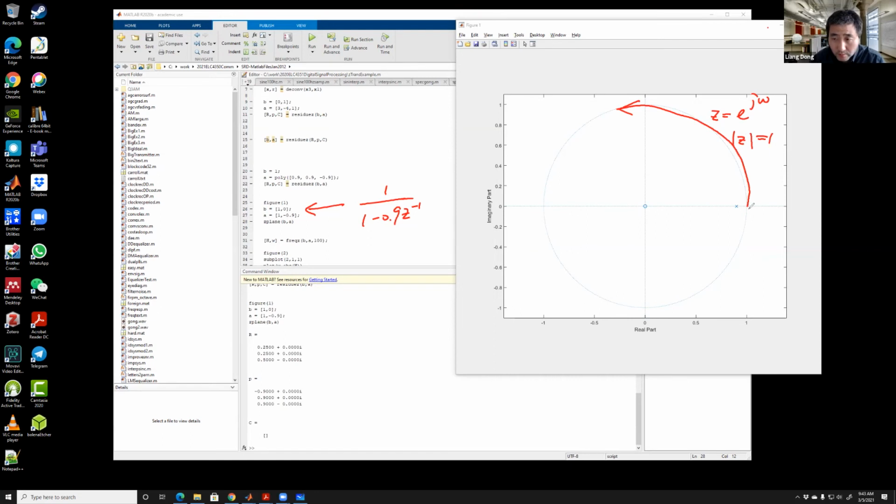So I also want to show the same B and A here. Now I know it's a 0 here, a pole here. Let's see how it looks in the frequency domain. Before I draw this out, I get a feeling I'm traveling along this unit circle. If I'm here at this point, which is DC, my frequency is 0, right? This frequency here is 0, and it's close to the pole. When it's close to the pole, the value of X(z) should be quite large.